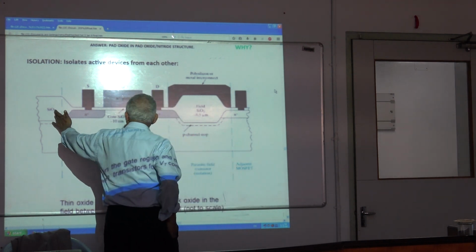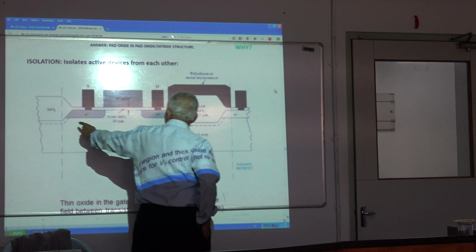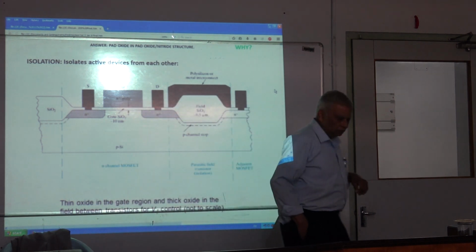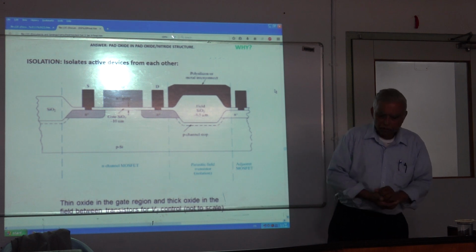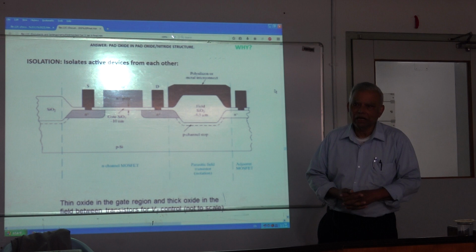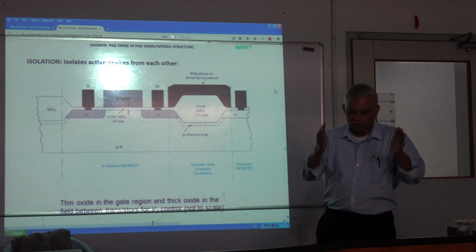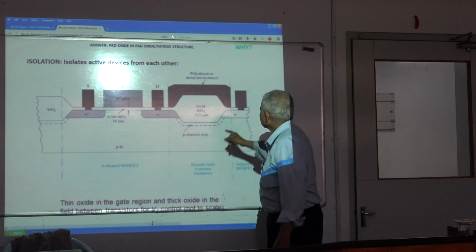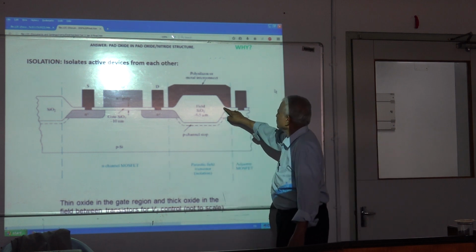Here's the so-called isolation oxide, which is the low-cost type of isolation. Nowadays, low-cost is all replaced by shallow trench, actually, it's STI. So we go more vertically down. We don't have this nutty problem called bird's beak.